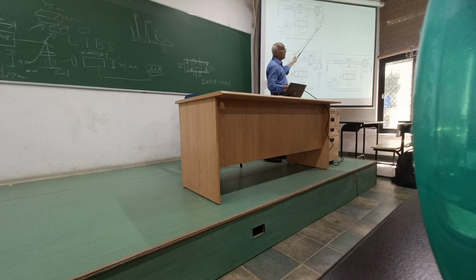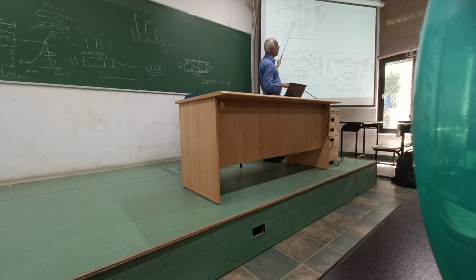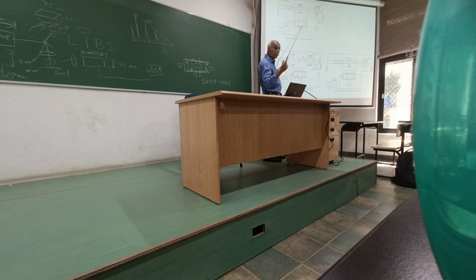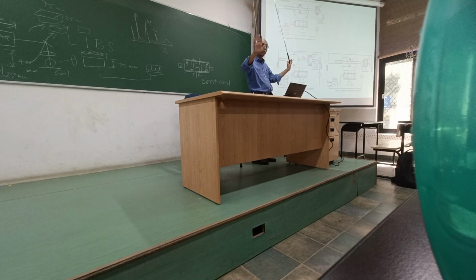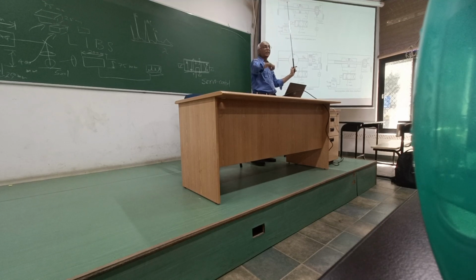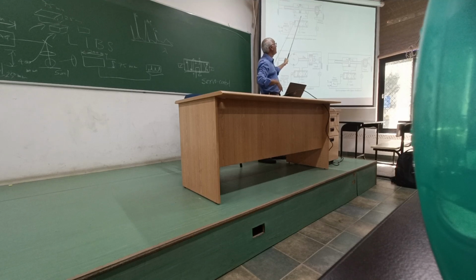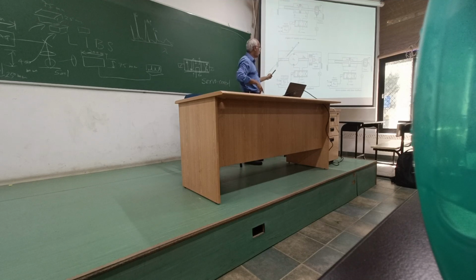Now, either you pick up from here, or within this control valve there will be a sensor to pick up position, displacement basically, and there will be a difference between this displacement and this displacement, of course. However, there is a relationship we know. So from this displacement, we will be able to derive this displacement as well, and pick up this signal and use it.